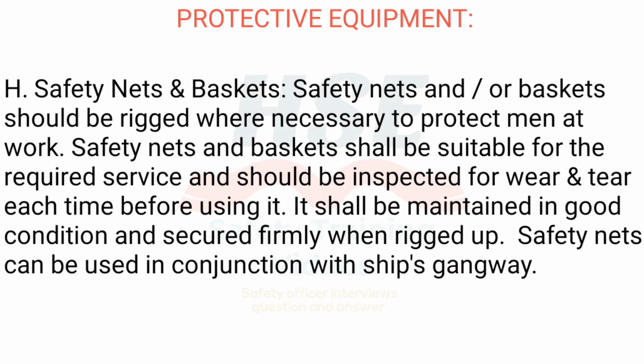H. Safety nets and baskets. Safety nets or baskets should be rigged where necessary to protect men at work. Safety nets and baskets shall be suitable for the required service and should be inspected for wear and tear each time before using it. It shall be maintained in good condition and secured firmly when rigged up. Safety nets can be used in conjunction with ship's gangway.